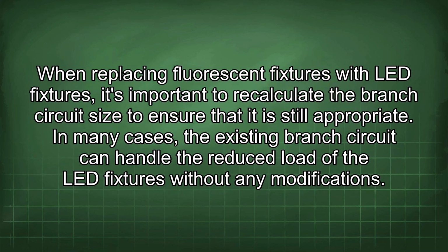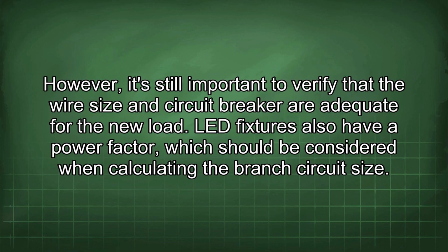When replacing fluorescent fixtures with LED fixtures, it's important to recalculate the branch circuit size to ensure that it is still appropriate. In many cases, the existing branch circuit can handle the reduced load of the LED fixtures without any modifications. However, it's still important to verify that the wire size and circuit breaker are adequate for the new load.